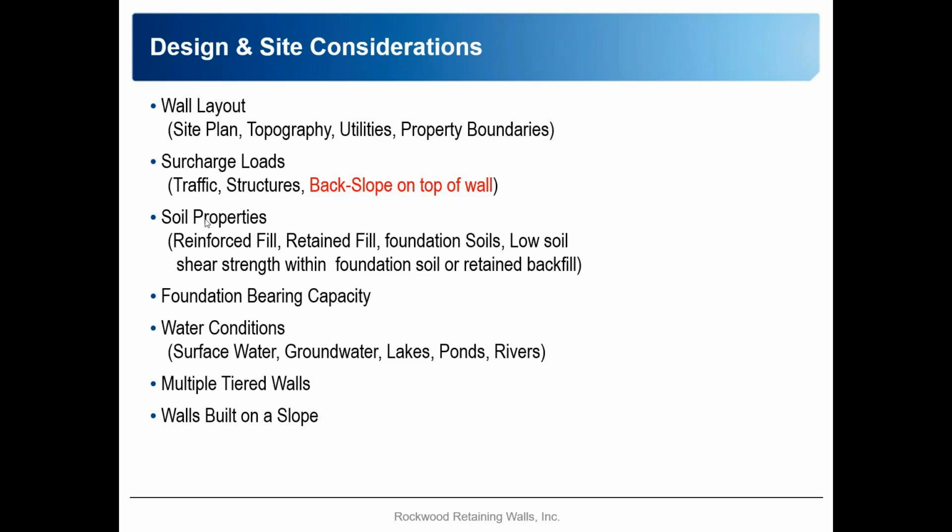So granular is good, silty clays typically are not as good. A lot of that is due to how they react to water. Retaining walls are built outside, they're going to get introduced to water.